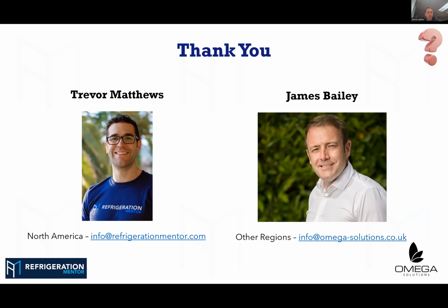But ultimately, if we've managed to tighten the expectation and reduce the expected line penalty by one degree, for argument's sake, we can assume that I work on 4%. Some people maybe say 3%, but say 3 to 4% saving for every degree that we can squeeze. So we effectively do everything as engineers and technicians to keep the suction pressure as high as we possibly can and discharge pressure as low as we can. So the software really does help and support energy efficiency through reduced system losses. And we're going to dive into that in week 3 anyway.